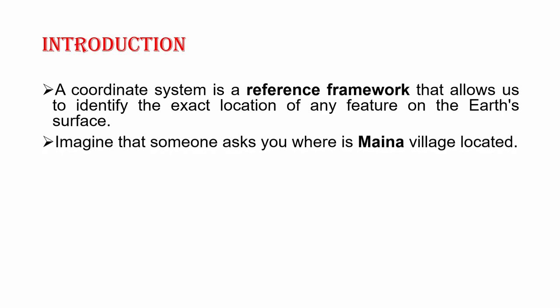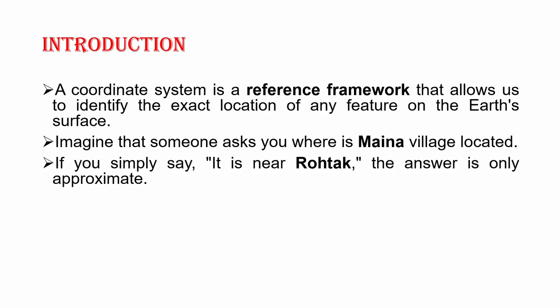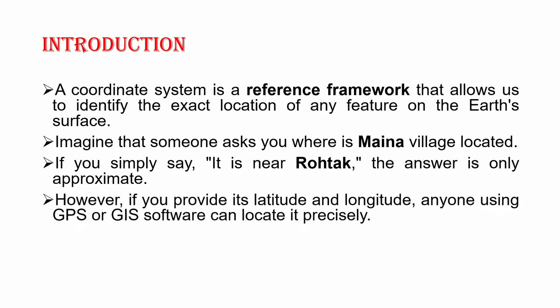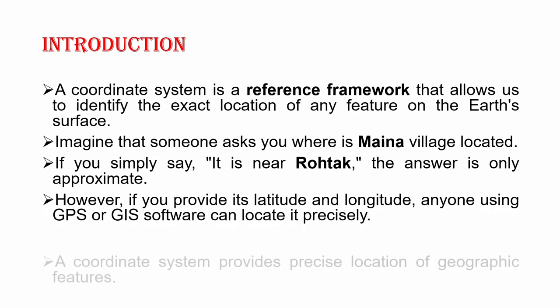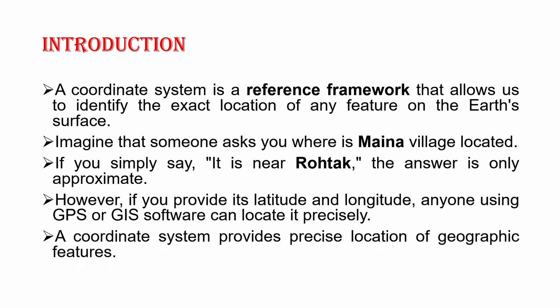Imagine that someone asks you, where is Maina village located? Your answer will be, it is near Rohtak. The answer is only approximate. However, if you provide its latitude and longitude, anyone using GPS or GIS software can locate it more precisely. A coordinate system provides precise location of geographic features,